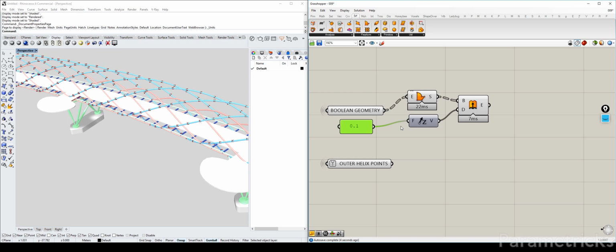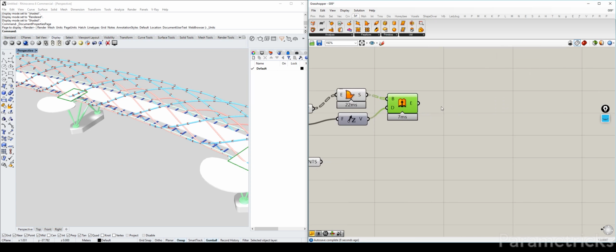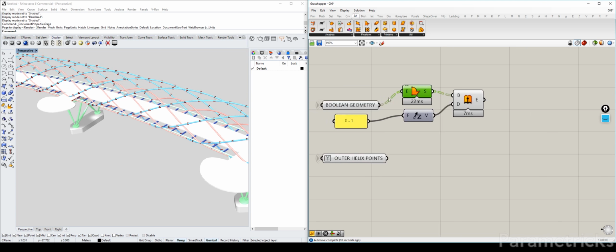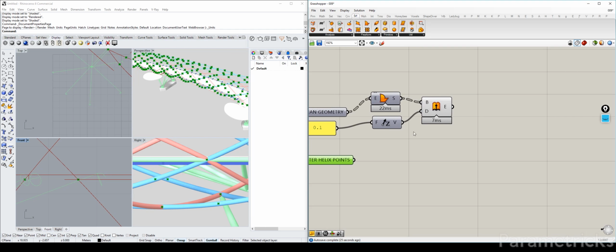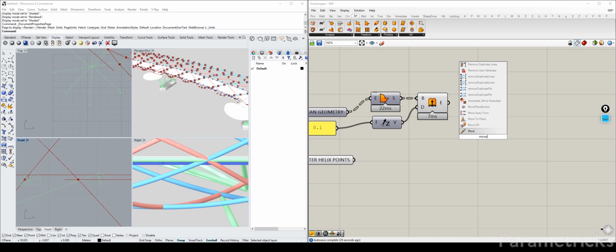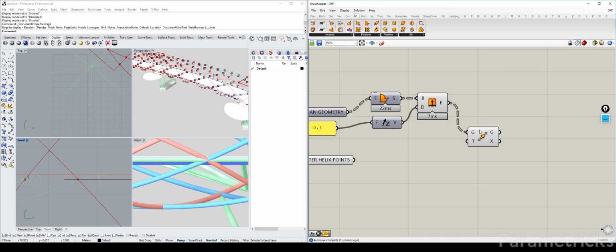But the important thing is that you just need a geometry, to test a solid geometry, and this is the way to do it. And one thing you have to take note of is if you look at our front view here, this is our geometry, and the point we want to test sits right on the edge of it. And just to be sure, what I like to do is move this geometry back down by half the extrusion height.